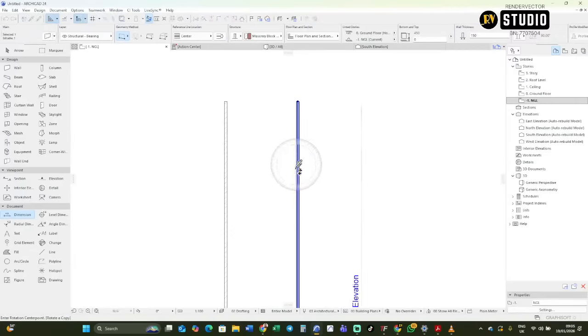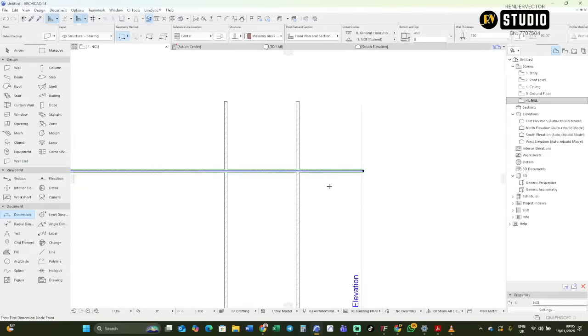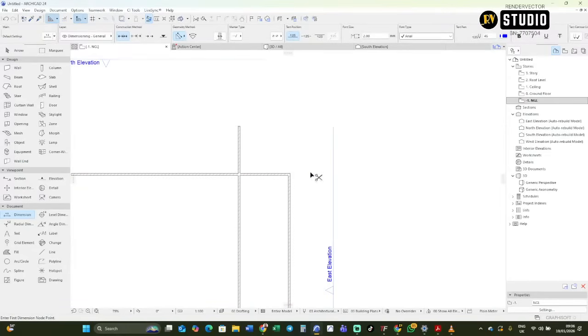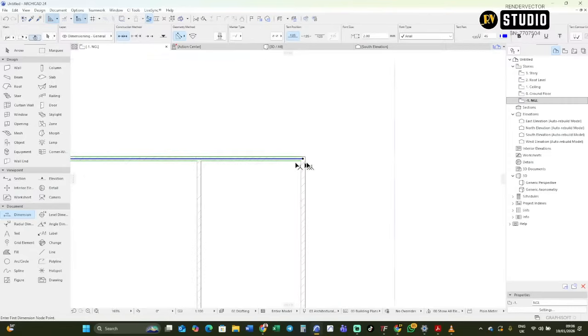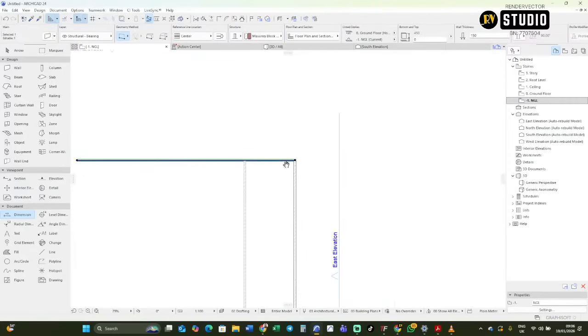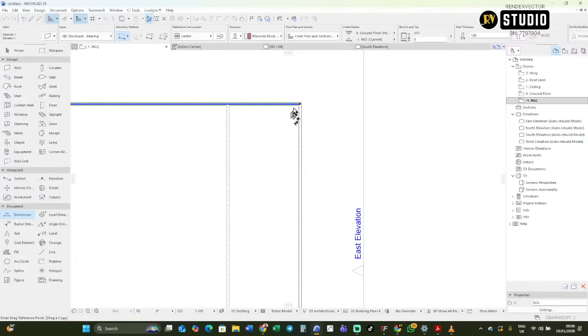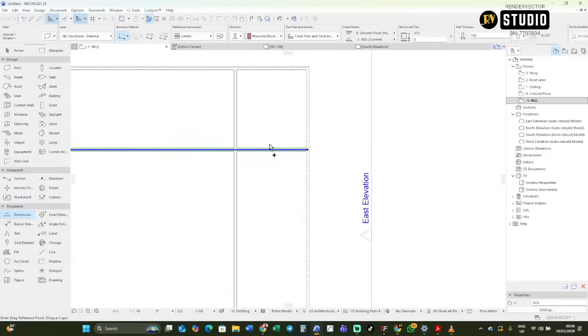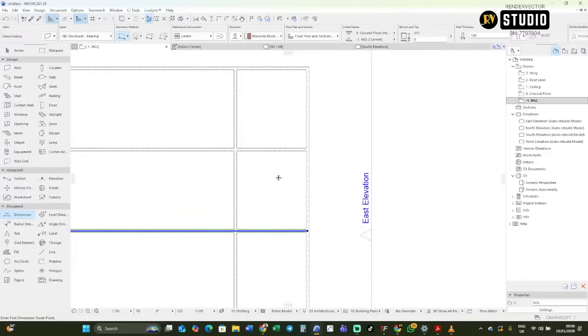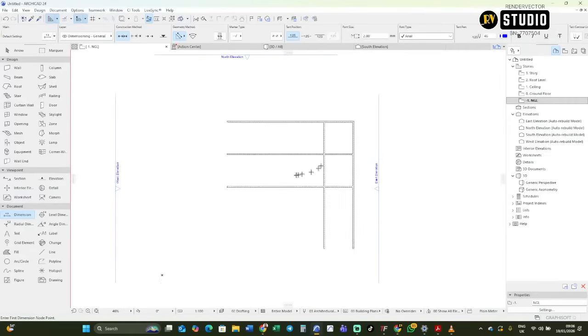Control Shift E to rotate a copy this way. So rotating it this way, I need to bring out a room at the edge here. When I hold this down, let me just make it 4000 internal because of the toilet and some other things. So Control Shift D, I'm going to hold my shift and press D. Let's say 4150, and then Control Shift D, the same thing, 4150. Yeah.